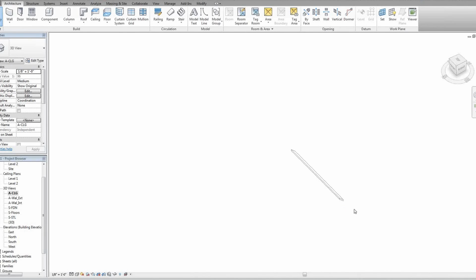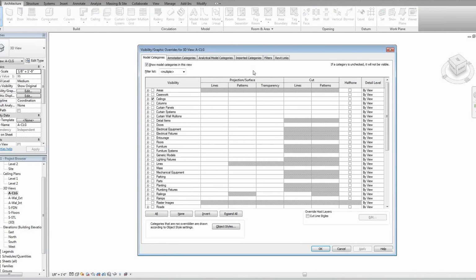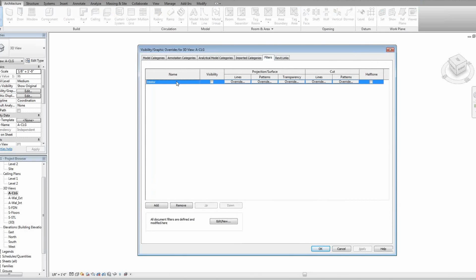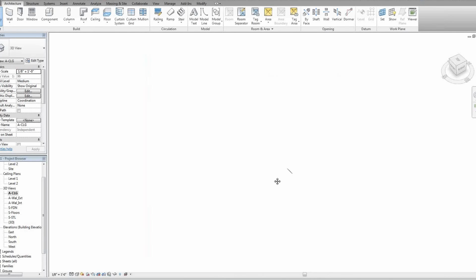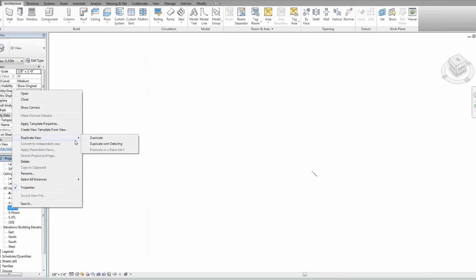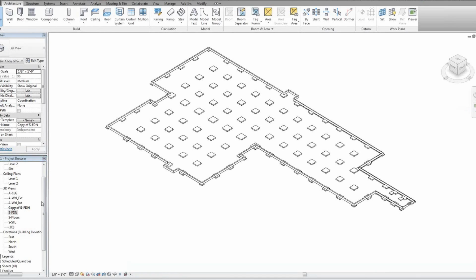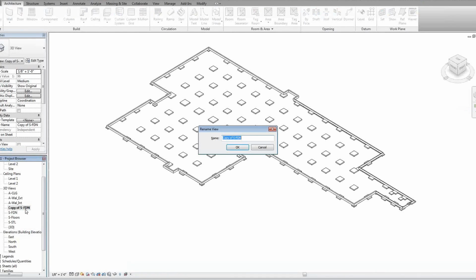So this model doesn't really have any ceilings modeled yet, so typically you'd see a lot of them, but they don't have it. I guess another thing, I've got interior things turned off, so that might also be affecting it, but it doesn't. They haven't modeled this yet. Okay, so let's do columns. We'll duplicate a structural view. So structural foundations. We'll call this.